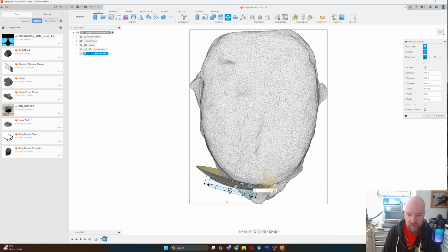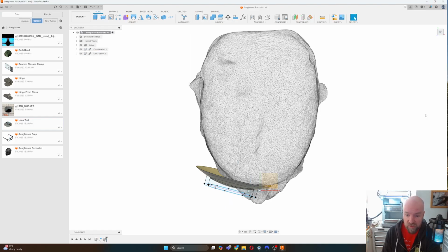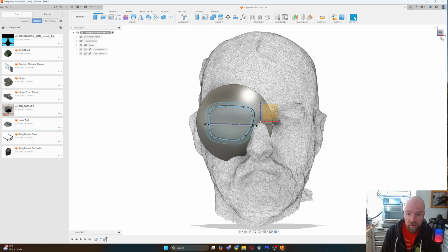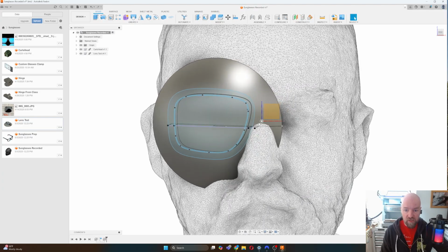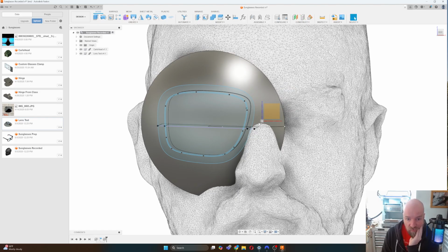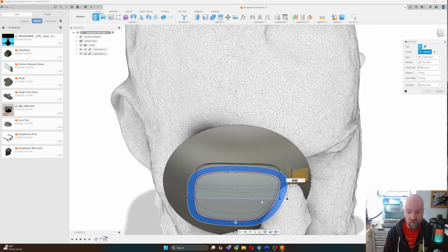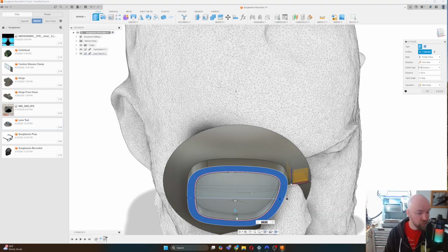How far we tilt these sunglasses will determine the thickness of the stock of material we need to cut this out on. So, I've got almost an inch thick stock, so we've got a decent amount of curve that we'll be able to put in here. Once I've got it positioned, I'm going to go ahead and say okay. All right, cool. That looks pretty good, I think. Well, I wonder if I should have extruded. If I click extrude here, oh yeah, it's going to extrude normal to the plane. All right, so that's good.